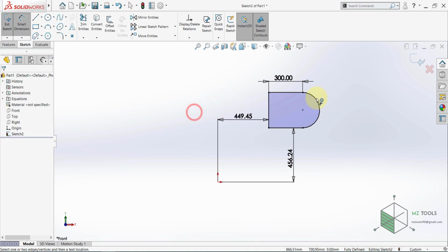If you have a look now, our sketch is black, and this has a meaning. This means that our sketch is fully defined now. In other words, we have 0 degrees of freedom, and you can tell here, fully defined. So our task from now on is to make all our sketches fully defined. So here, instead of having this distance and that one, let's delete them.